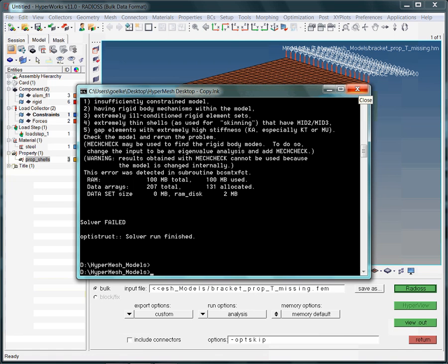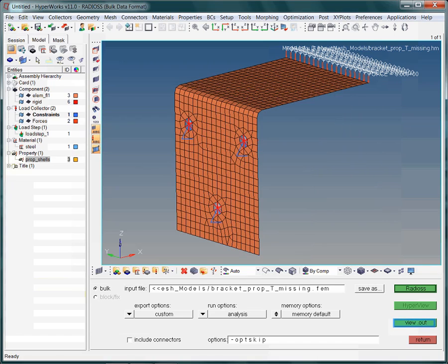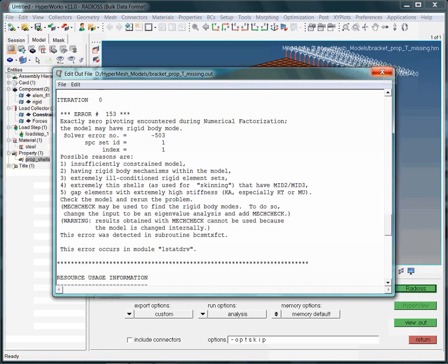In the first instance, the length of the error message may be a bit frustrating. Stay calm, as you will see, it isn't that complicated. Surely, we should view the analysis log file, not only due to the length of the error messages. The log file provides several hints regarding likely model errors. Where to start? As indicated, the model may not be sufficiently constrained.